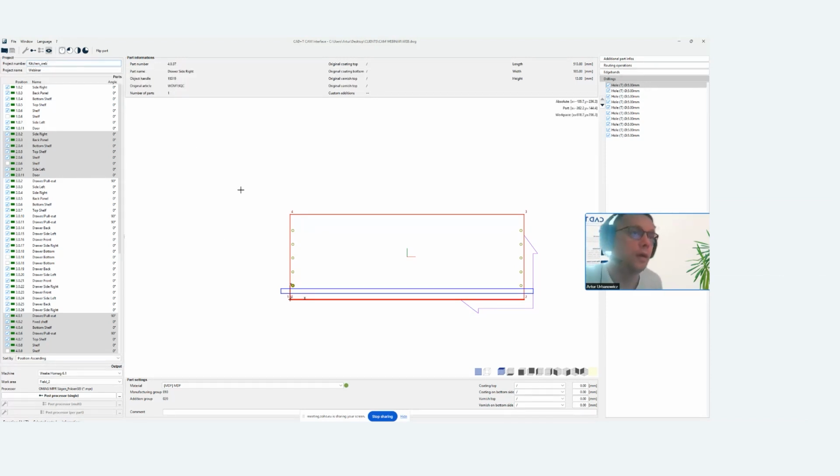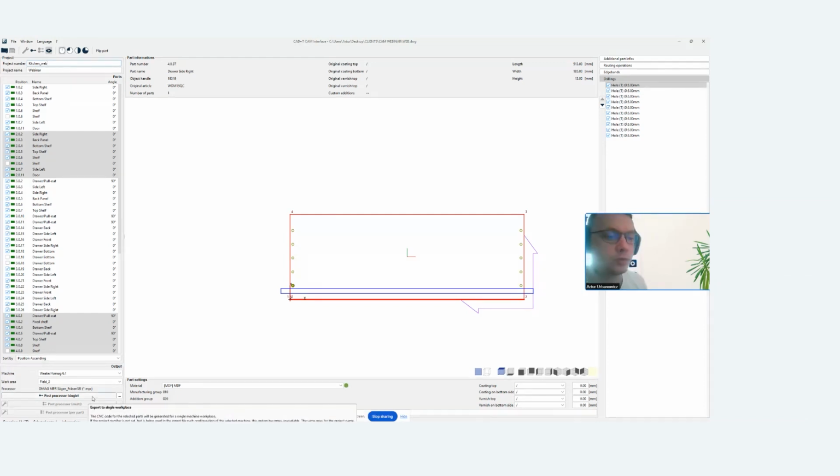Now, once we have filled these windows up, then we are able to generate a post processor. Some of you could have different options. Some of you could have the multi activated. It's for multiple post processors, but when you've got only one CNC machine, the single is enough.